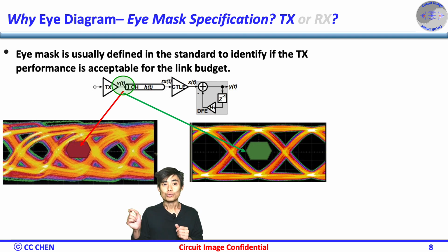Again, when the chip came back after the verification, the engineer would apply the eye diagram on the silicon and provide the data to the circuit designer for correlations. Of course, during the test validation, everything could go wrong, and the measured eye diagram helps the debugging process either in the design or the testing programming settings.